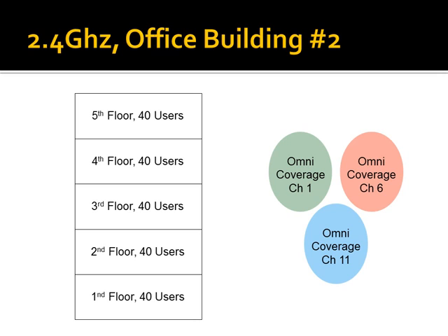Remember, that's one that we've defined, pardon the pun, kind of broadly to have an azimuth pattern that is fixed across whatever we state as the angle here, and a fairly narrow vertical pattern, except I'm going to change this to 120 degrees. Okay? 70 users, you can use 120 degree sector or omnis.